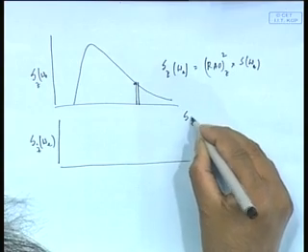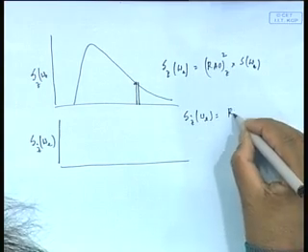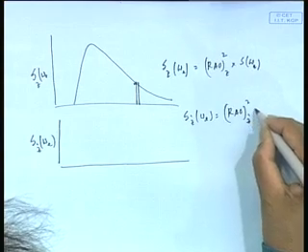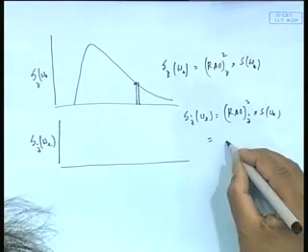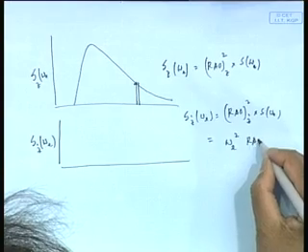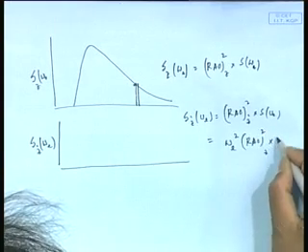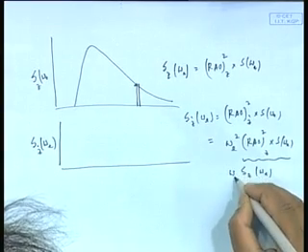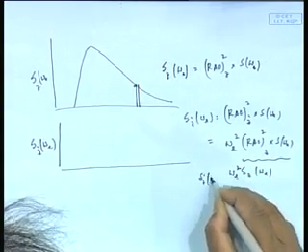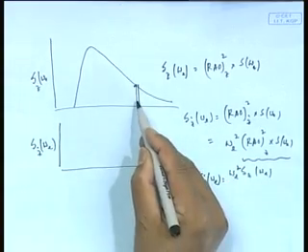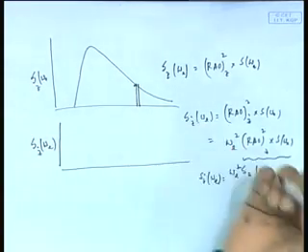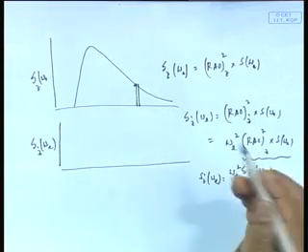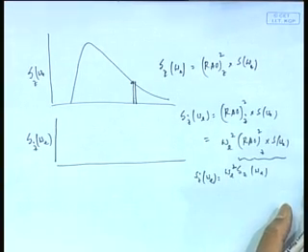Now, this value SZ dot omega E is supposed to be RAO Z dot square into S omega E, that is equal to omega E square RAO Z square into S omega E. This is equal to omega E square SZ omega E. So, in other words, all I have to do is to multiply by this omega E square to get the value. Okay. See, this is interesting. Therefore, the velocity spectrum is obtained from this simply by taking each ordinate into omega E square corresponding value.